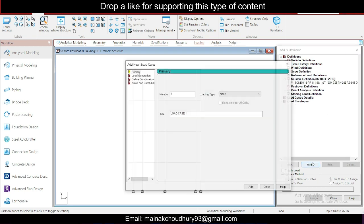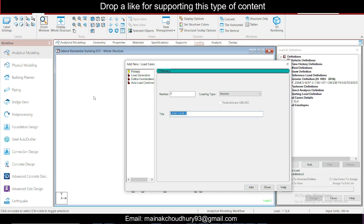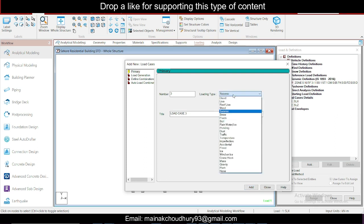Remaining cases obviously we'll add in the STAAD editor. If you add load combination, there is no need to add HL plus X plus Z, because in load combination anyway plus and minus are considered, so there is no requirement for that.